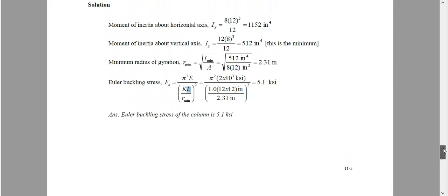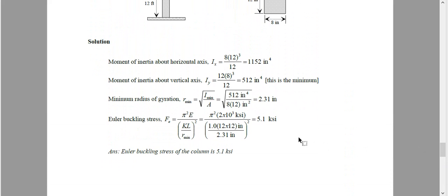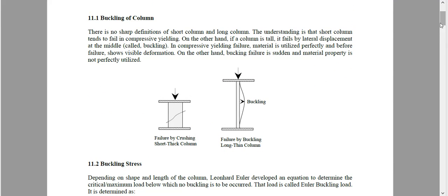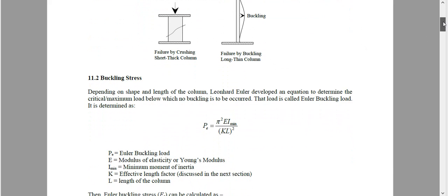Okay, so we covered in this very short chapter what the Euler buckling load and the Euler buckling stress are. So what is this? It is the load or stress at which a column will start buckling. We do not want the column to buckle. Why? Because then we cannot use the material properties. Its failure is by geometry. We try to avoid this. So how to find it?